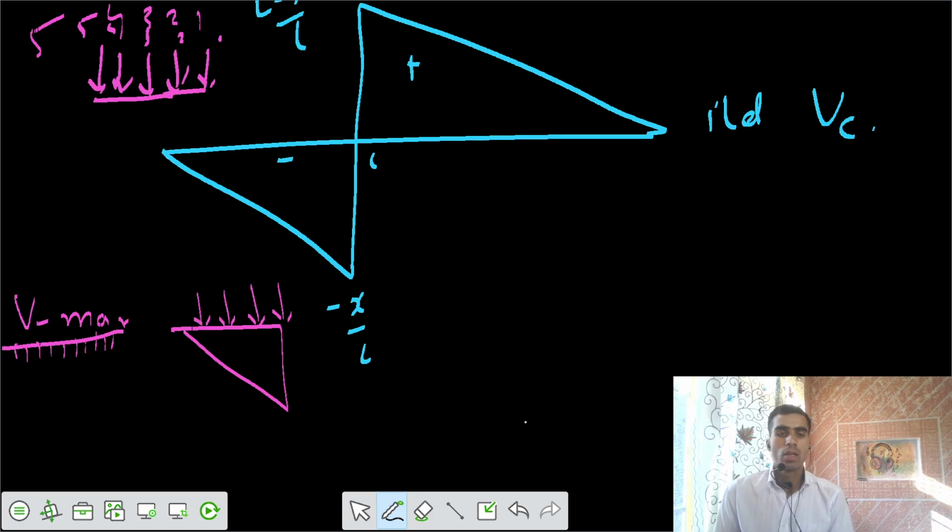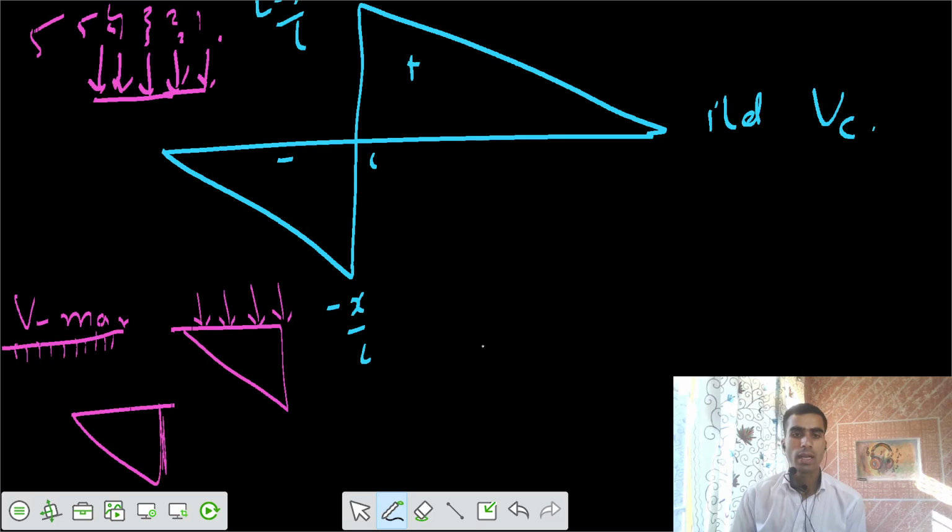So this is your case one, and it depends on the loads, what is the peak load we have out of those, and it depends on the center to center distance between them. Accordingly, we have to perform different number of trials in order to get the maximum value of that shear force. There might be a chance where you place some loads on this side, the negative side, and a few loads on the positive side also, and still we can get V negative to be maximum.